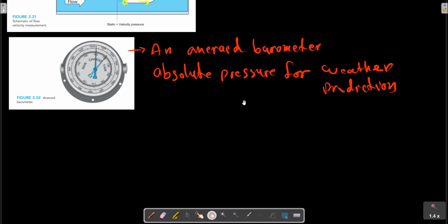Numerous types of devices are used to measure temperature. Perhaps the most familiar of these is the liquid-in-glass thermometer, in which the liquid is commonly mercury. Since the density of the liquid decreases with temperature, the height of the liquid column rises accordingly. Other liquids are also used inside thermometers, depending on the range of the temperature to be measured.